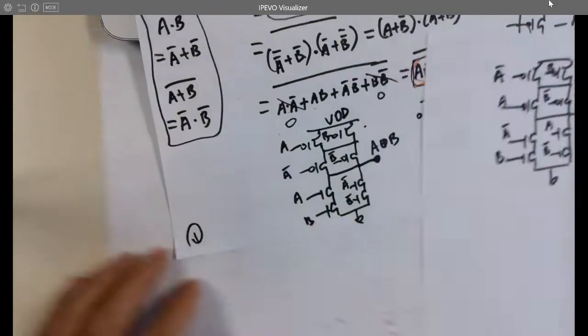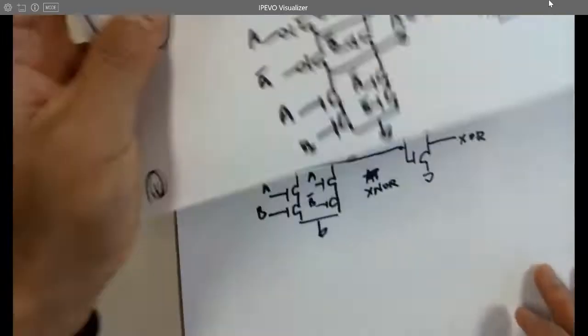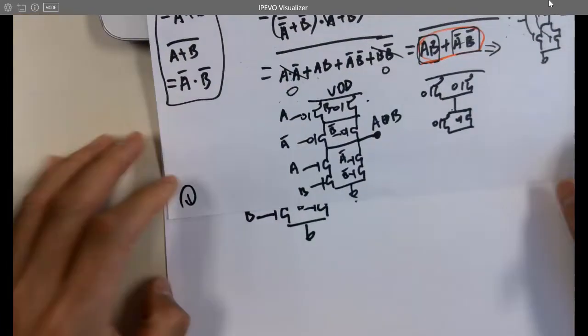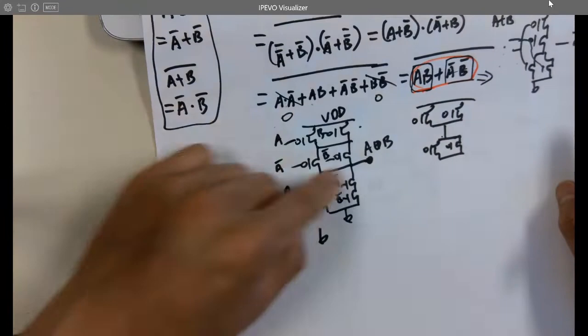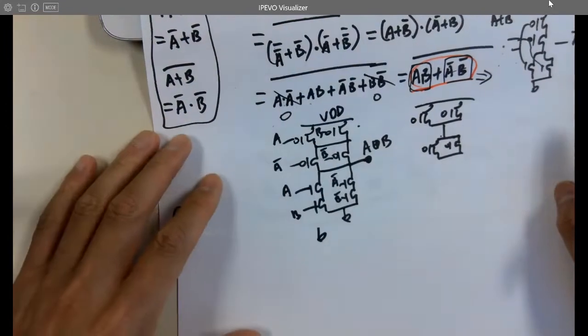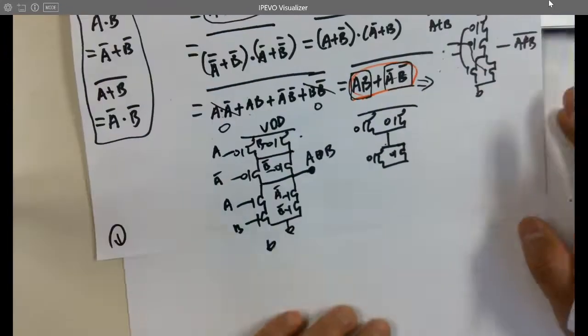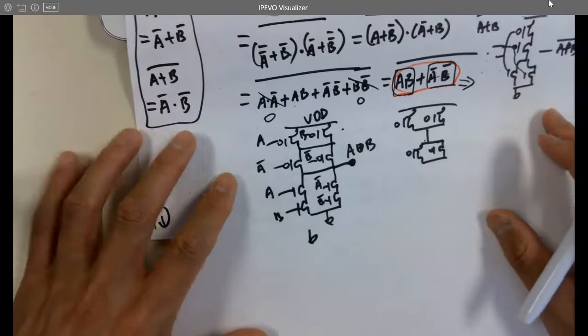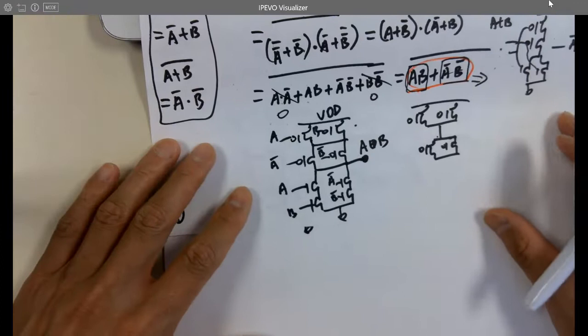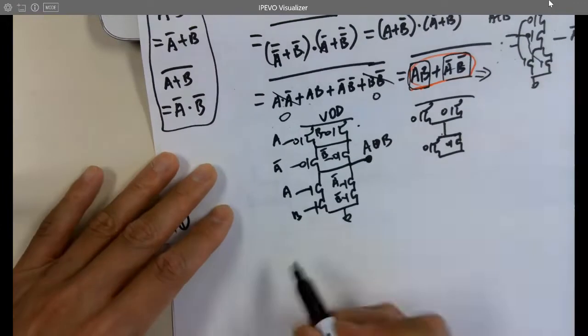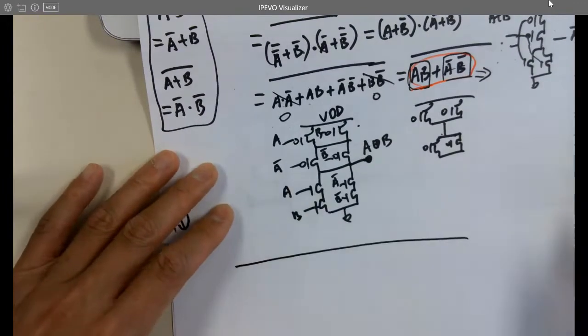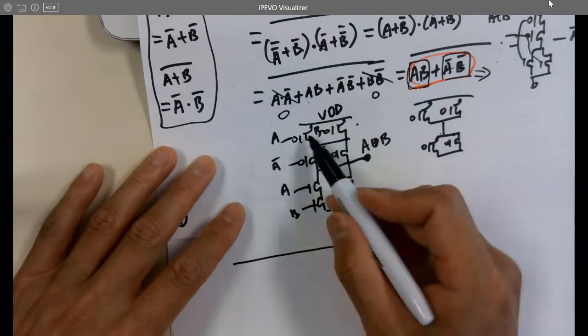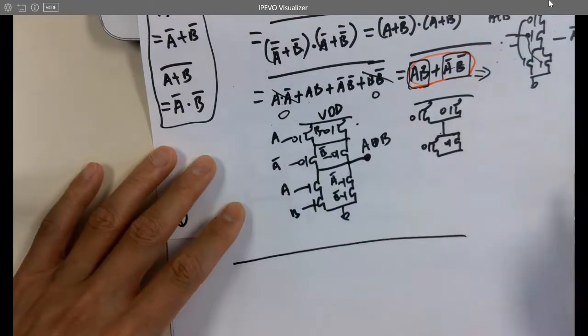Now we know the schematic, and we need to move forward with layout. So by looking at this schematic, how do we design the layout? It's pretty fun, I like it a lot. How do we do the layout? Two rails, right? PMOS, two PMOSes in parallel. So four PMOSes, right? Four PMOSes.